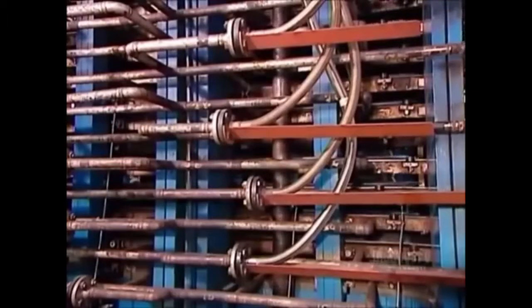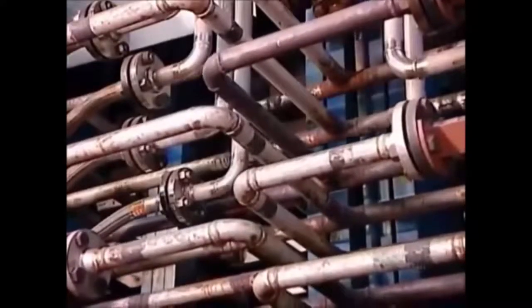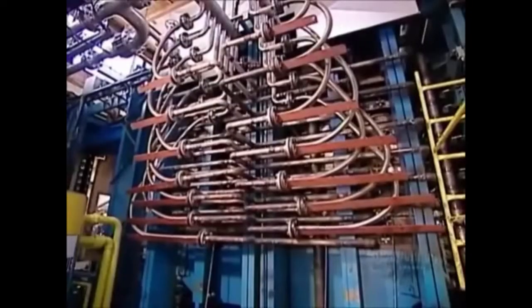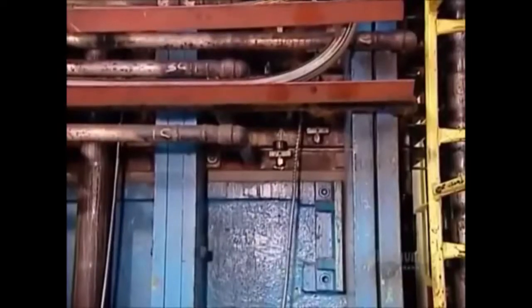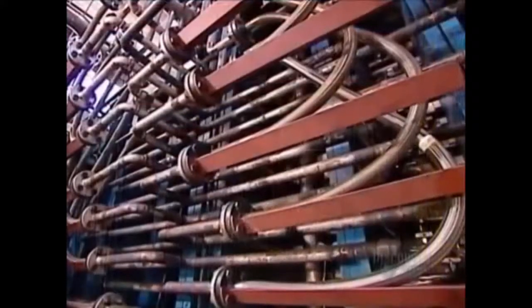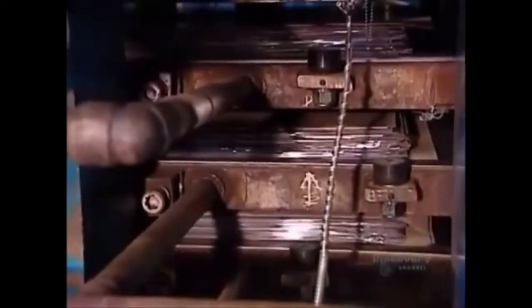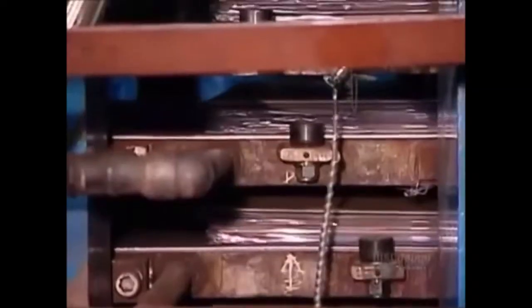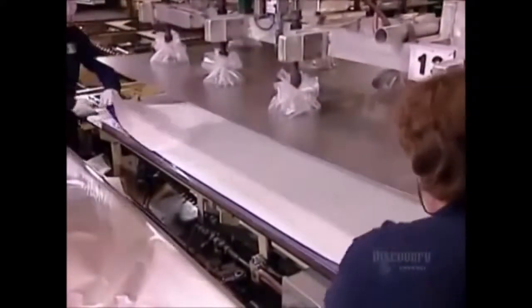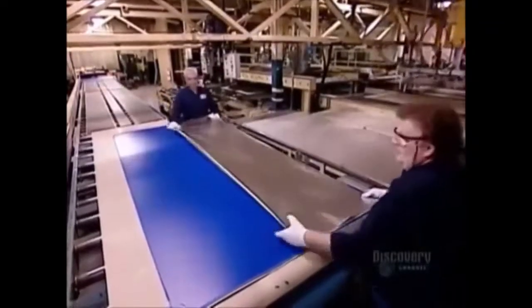Everything now goes into a press. The intense heat and pressure compress the layers. The overlays bond to the printed papers, and the saturated craft paper bonds to each decorative layer, creating laminate sheets. The textured plates between each set, meanwhile, imprint their pattern onto the heat-softened resin, texturing the laminate surface. The laminates come out of the press fully cured.